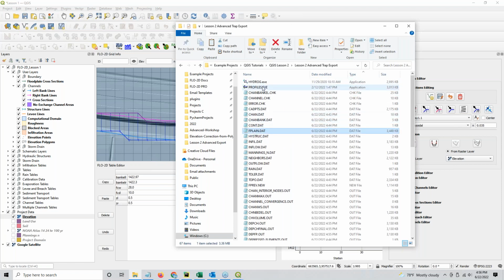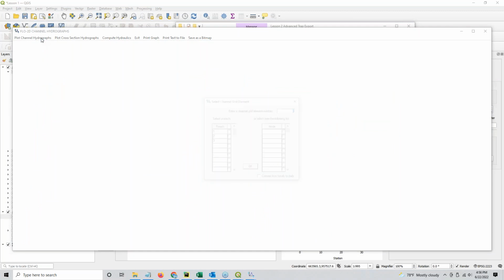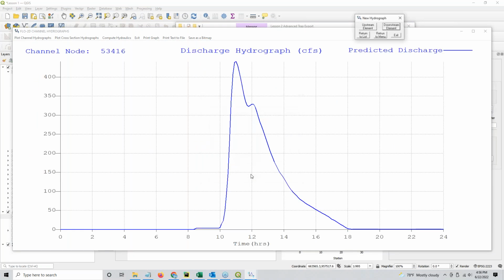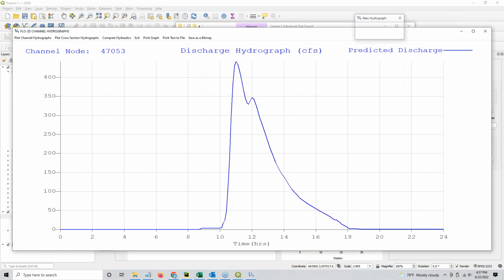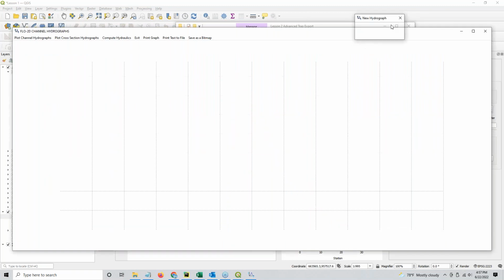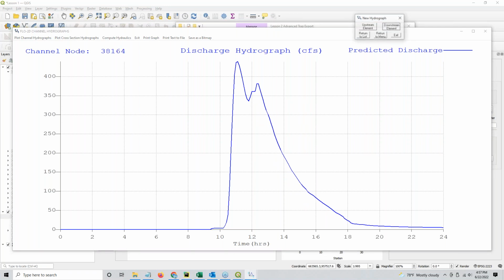So let's check the hydrograph, and we're just going to start from the one, and we had about 400 CFS in the previous model. The dimensions are basically the same. And there's rainfall on this too, so it should be increasing as you go downstream. The two peaks are going to be slightly different.